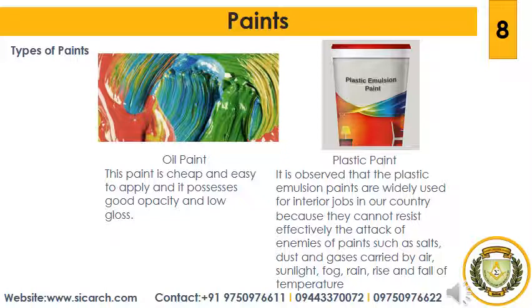If dark color plastic emulsion paints are required, they should be used as made by the manufacturers. For light color paints, a white emulsion with certain other colors known as the tinters may be added to the paints made by the manufacturers. So the next is about diluting the paint.